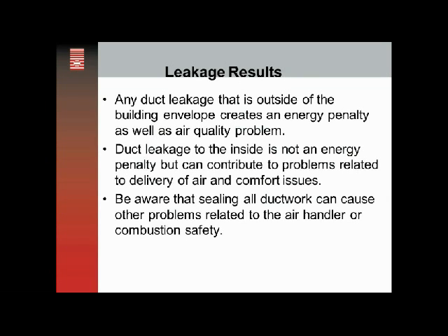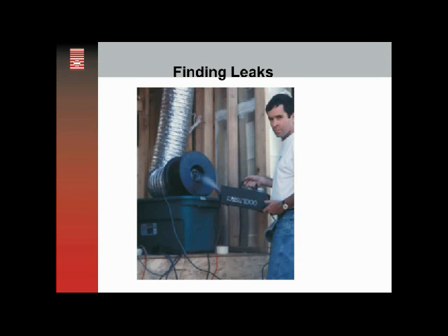that the system's approach demands that you look at all of the various interactions that may occur when you change something in a building envelope. Sealing ductwork can create problems, and last person out always wants to do a safety check, or a worst case draft test, or a CAS test, combustion appliance zone safety test, on the building to make sure that you haven't either created a problem or exacerbated a pre-existing problem.